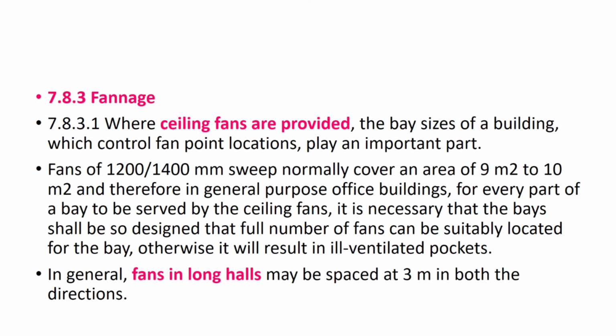Now, we were talking about if the allowable bearing capacity is available only at a very great depth, then how do I rest the foundation? And that too at a higher elevation. What they say is that I can go for an incompressible fill material, for example, sand or gravel, in which case the width of the fill should be more than the width of the foundation by an extent of dispersion of the load from the base of the foundation on either side at the rate of 2 vertical to 1 horizontal. Now what he is trying to tell is that, again I don't have that particular blackboard to explain to you, see what he is saying.